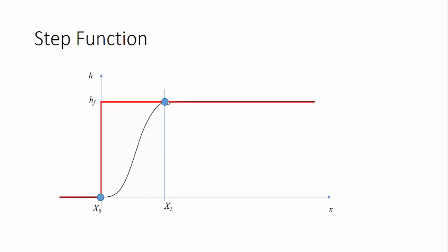This step function will define the change in the speed as a function of a certain variable. The variable that we'll have is our time, so the x-axis is the time. We are going to tell Adams to start changing the speed from 0 to this high value such that it will start smooth at time equal to 0 with 0 velocity, and then it will ramp the velocity up until it reaches the maximum value at this time.